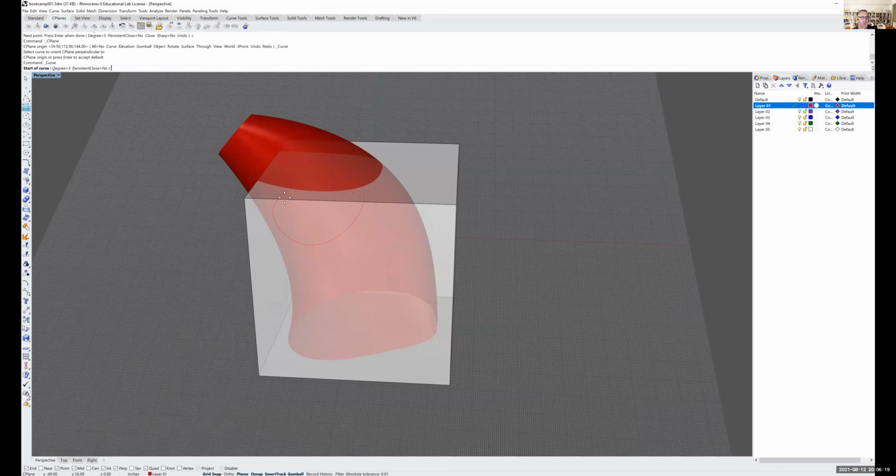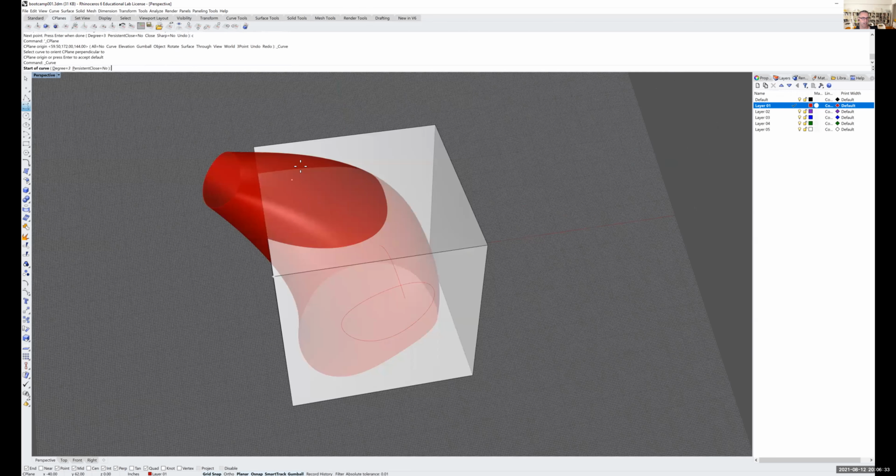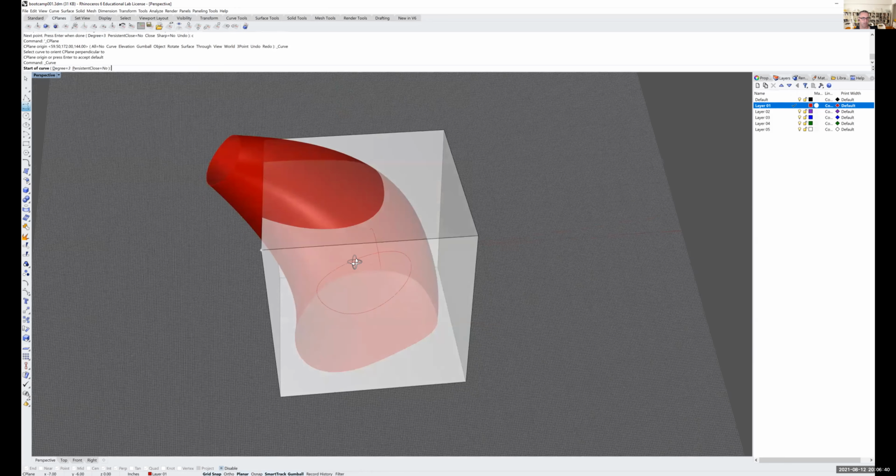And we saw last night that the snaps will override the construction plane. It's really simple, just come down to the bottom and there's this disable down at the bottom. So if you're like, I'm starting to have a lot of geometry in here and as I draw this last shape, I don't want it to snap to anything, I can disable my snaps for just a minute.